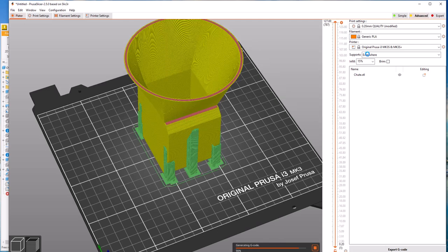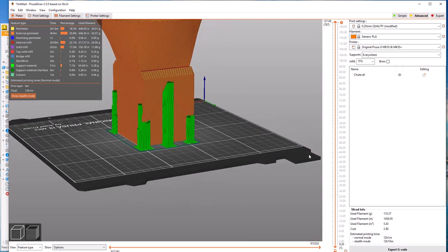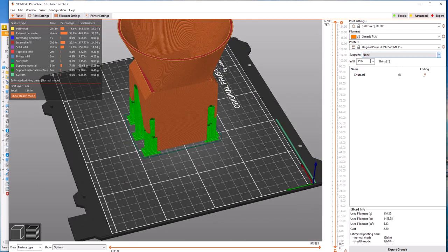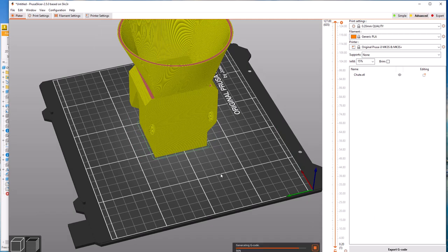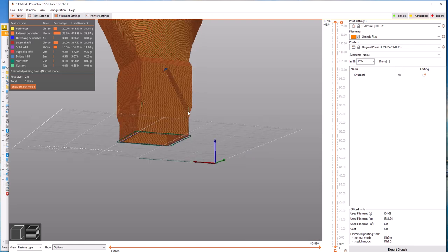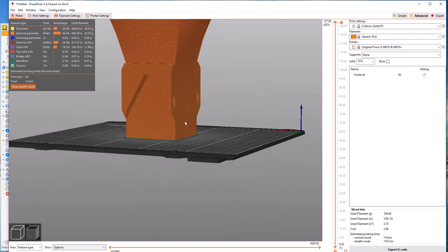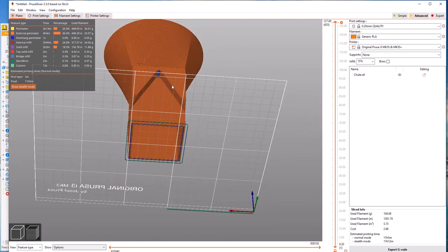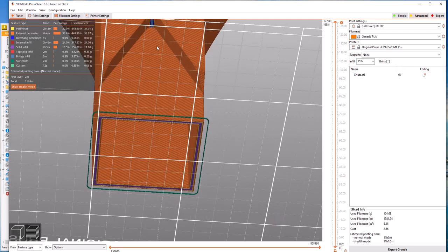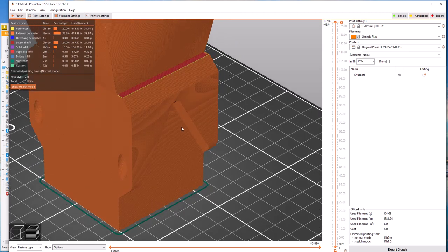And remember, we still have supports turned on everywhere, so it says, okay, we could still run some supports into those areas. But if I turn them off, I don't think I really need those supports anymore with the way this is designed, because we have a draft angle here, we have a nice clean angle right there, those holes going in are supported at some nice angles. The only thing that might be a little iffy is this area right here when it prints that top, but the way this part's designed, that is not a crucial area, so if it messes up on a layer there while it gets that roof, it'll be okay.